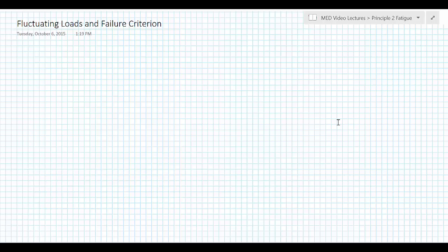Welcome back. In this video, we're going to discuss exactly how we get to the more general failure equations. That's the Goodman equation for fatigue failure, or the ASME elliptic. There's also a Gerber failure criterion. There's several different theoretical approaches to calculating whether or not a material will last 10^6 or 10^8 cycles. But we're going to look at how we get to those, and to do that we need to look at the more general case.